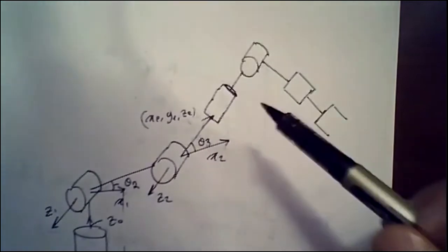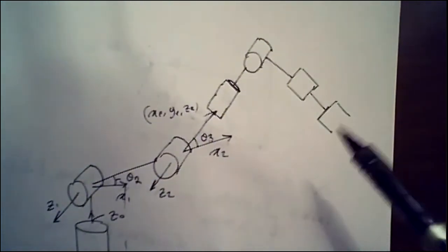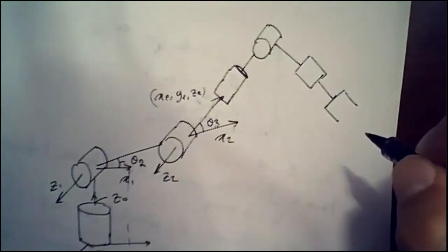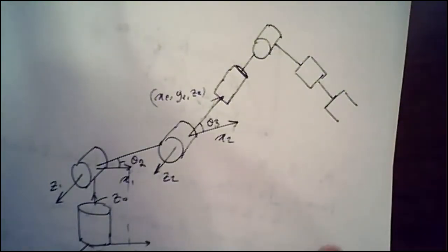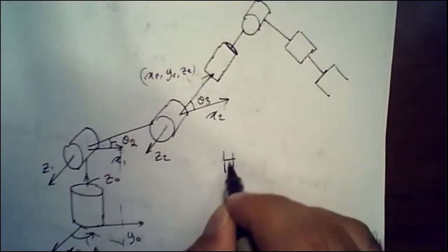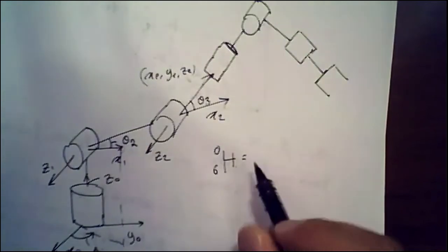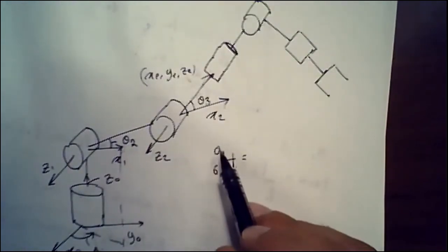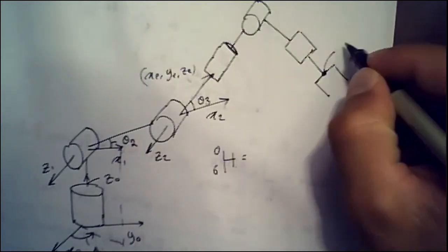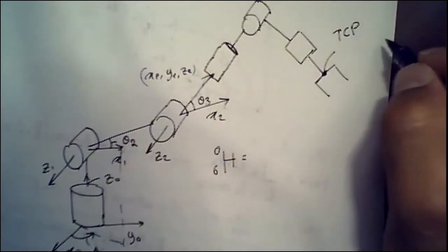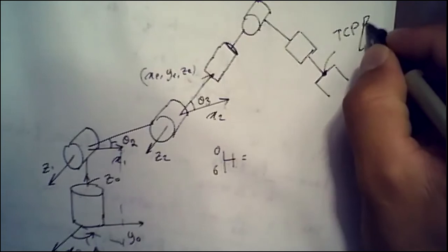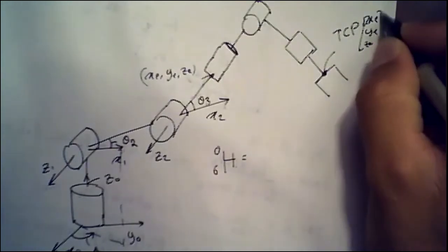But what is more important about this is the following. Let's say I would like to point this toward this direction, the direction that I have. When you are doing inverse kinematics, you will specify your H06. You guys agree? I think all of you will agree. When you are doing inverse kinematics, you know H06. H06 is basically, now this is my end effector. This is called TCP, tool center point. And this is my XE, YE, and then ZE.